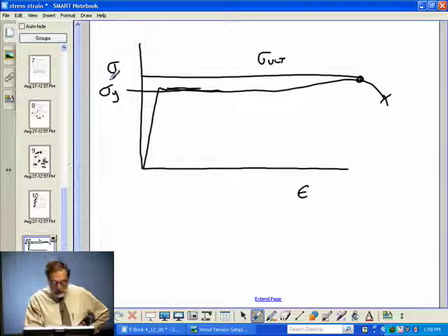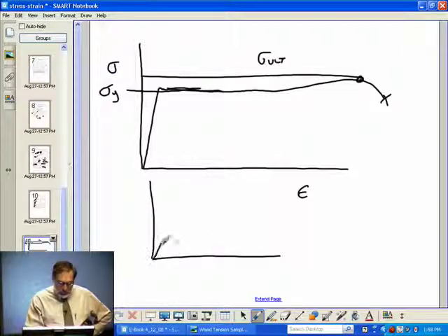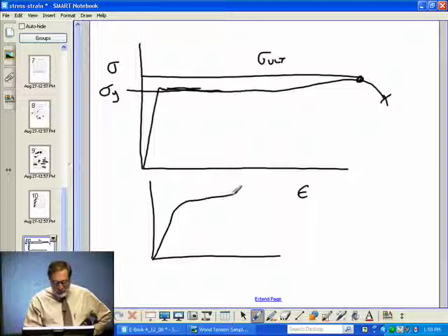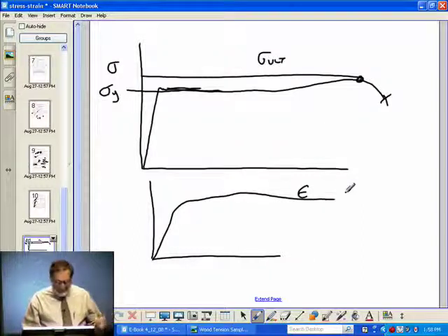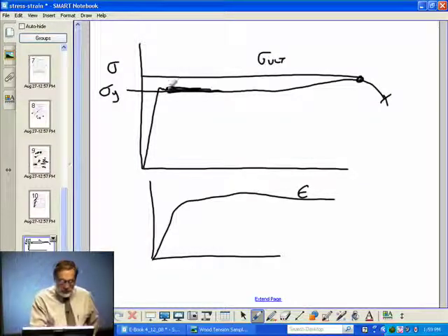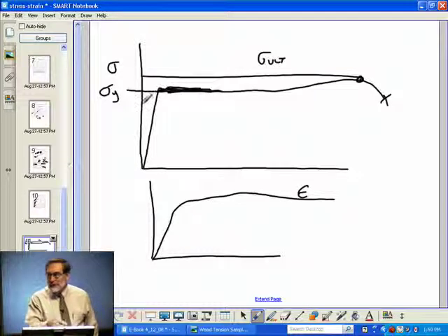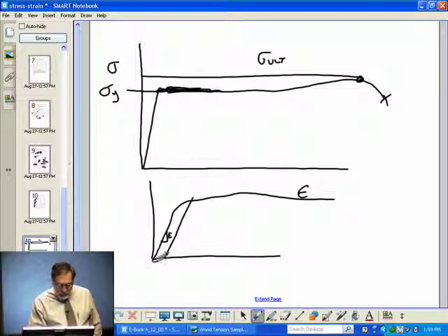Aluminum, which is more like the curves that we looked at before, is straight and then kind of rounds off and does something like that. We don't have a flat spot up here, where we'd say, well, that's good enough, we'll just keep it below that and it's close enough to wherever that point is. So we got our E here, that's no problem. What we do is we come over here and we have what's called an offset. So this is the offset strain.